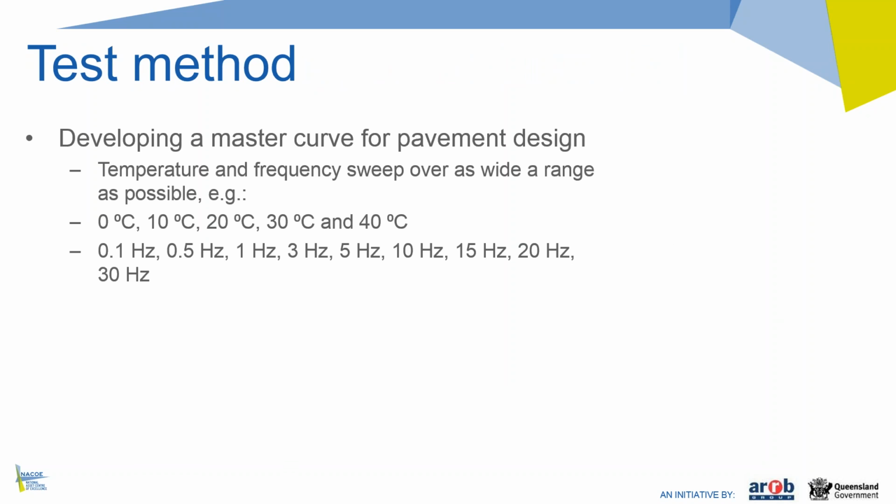Then in terms of the test method, to develop a master curve, we want to do a temperature and frequency sweep over as wide a range as possible, just because we then get the best definition of our master curve. So you want to be doing testing over a range of temperatures, and the temperatures shall not be more than 10 degrees apart. Also, the range of temperatures that you can actually physically do in your equipment will depend on the quality, if you like, of the thermostatic chamber, so your temperature cabinet.